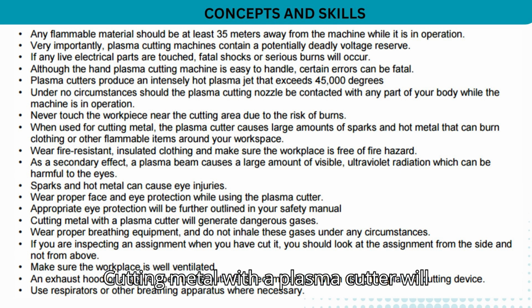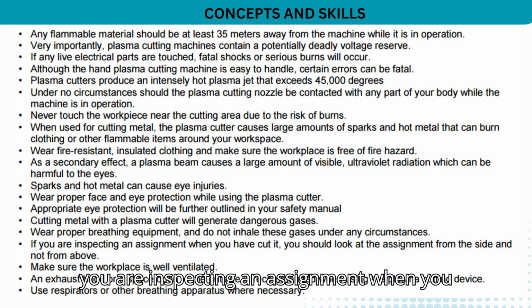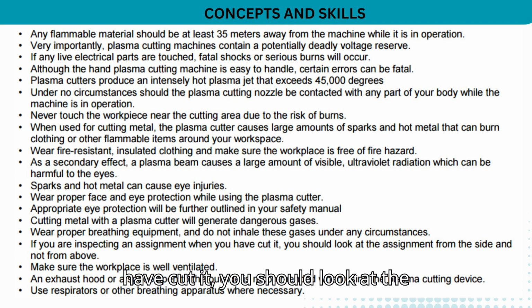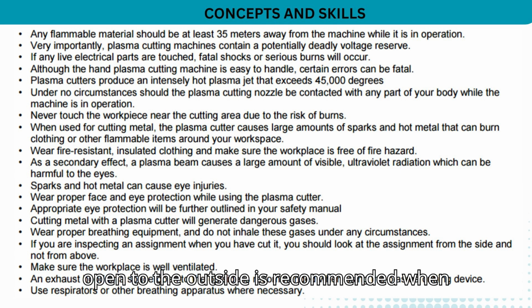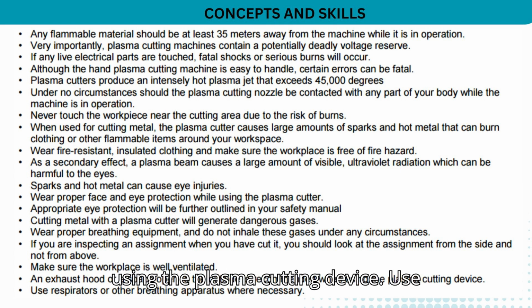Cutting metal with a plasma cutter will generate dangerous gases. Wear proper breathing equipment, and do not inhale these gases under any circumstances. If you are inspecting an assignment when you have cut it, you should look at the assignment from the side end, not from above. Make sure the workplace is well ventilated. An exhaust hood or a space open to the outside is recommended when using the plasma cutting device. Use respirators or other breathing apparatus where necessary.